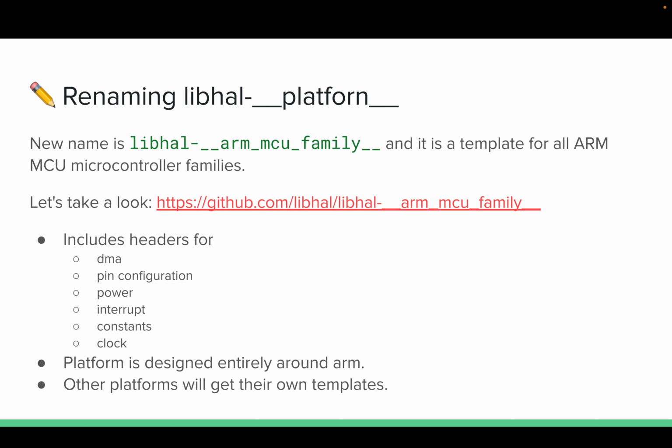And some of the other things that you need to implement, which will make it easier for developers to actually build out your libraries, would be power control, pin multiplexing or pin configuration. Sorry, I was yawning. Clock tree, and finally, direct memory access, DMA. And not all devices are going to have DMA. Not all devices are going to have a very sophisticated clock tree. I assume they'd have a basic one, though. I assume almost all devices have multiplexing, pin configuration.